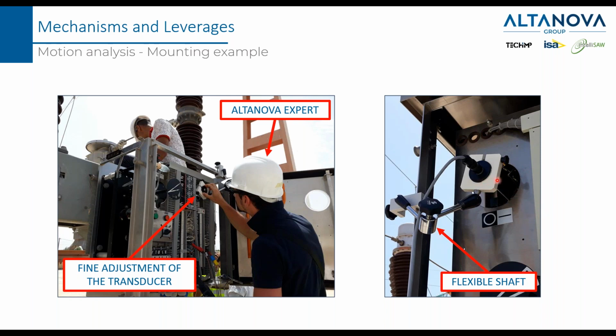If you open and close the breaker and you see vibrations in the transducer, this means that it's not well placed. You are then measuring the vibration of the transducer instead of possible defects in the breaker. So the positioning and the mechanical coupling of the transducer is extremely important to avoid confusion. You don't want graphs distorted only by a bad mechanical coupling of the transducer.